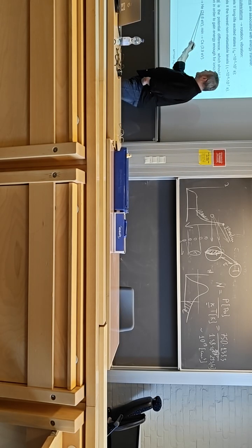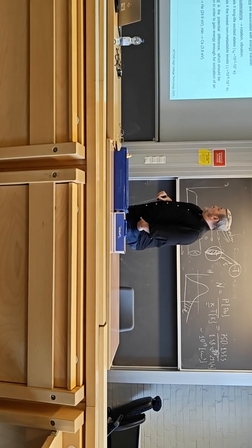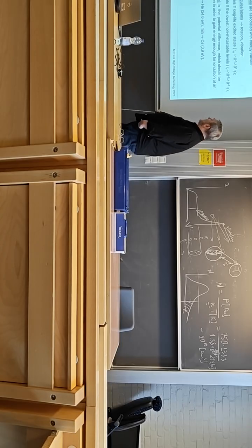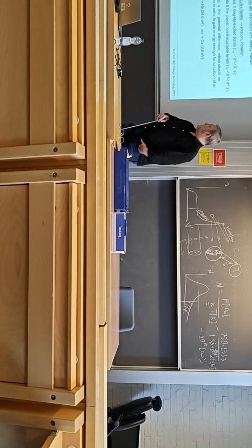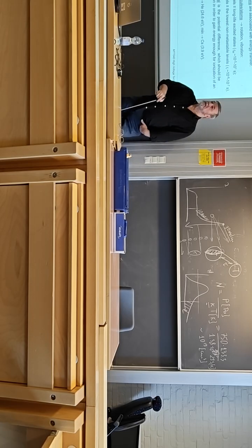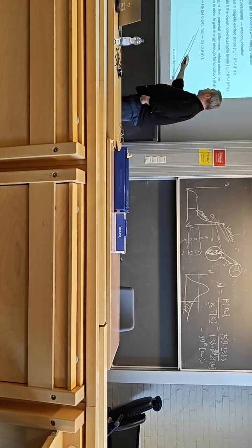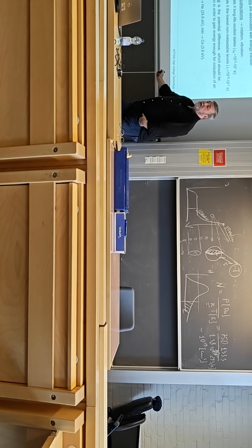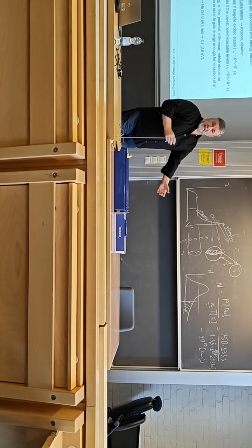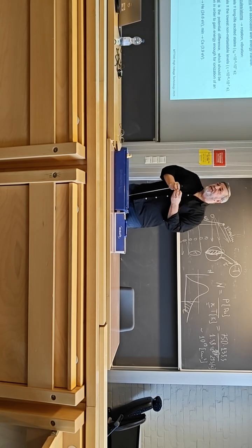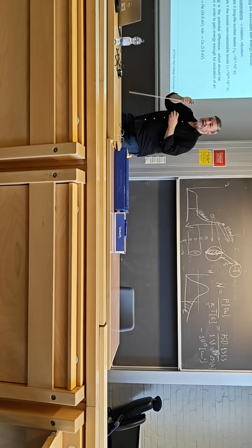Surprisingly, the highest ionization potential is up to 25 electron volts, and one can expect that this is the strongest gas, because you have to have enough energy. But this is not really so, it's one of the weakest gases, because ionization is not only about how much energy, but also about the cross section, how you transfer this energy to the electronic shell.